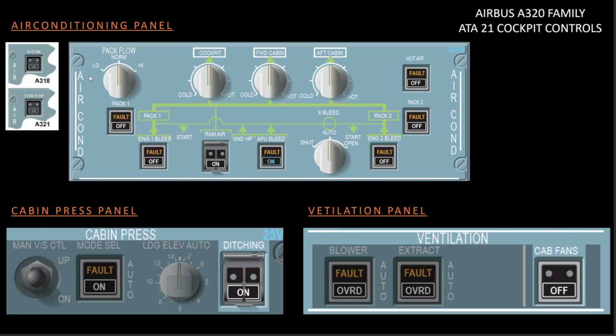And so, what will be controlled by this rotary selector? If you can remember, I told you that the flow control valve has a torque motor to position it. We talked about the flow control unit where you get the flow control valve, and there I told you that there's a torque motor which controls the position of the flow control valve.